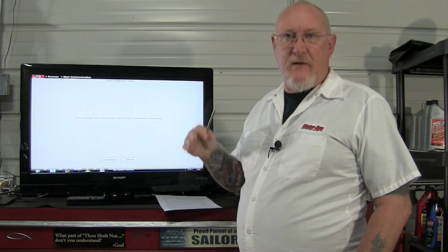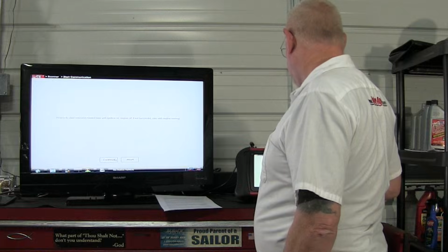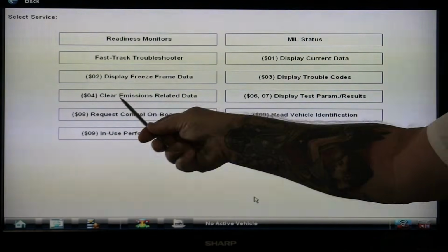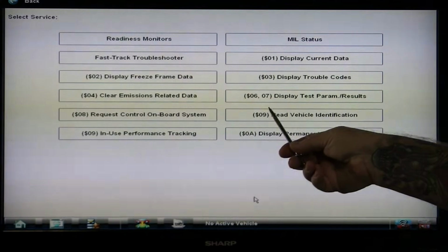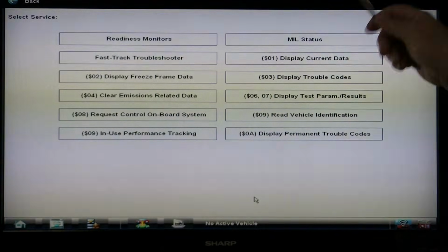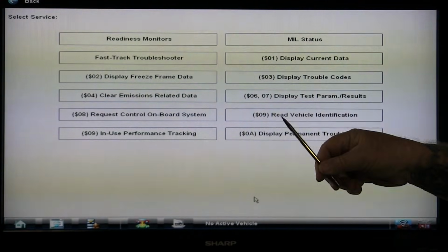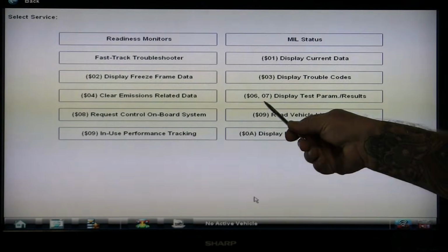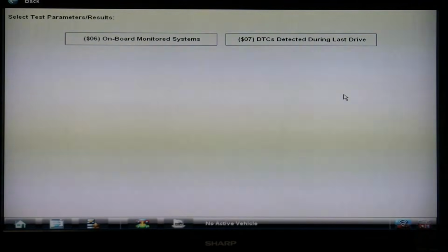Take a screenshot of it, take a picture of it with your phone, whatever you've got to do so that you don't lose that valuable information. Now lastly, you're going to see here there is no mode 5 listed on this screen. Now why is that? Pete, didn't you just say that all the Global OBD II stuff is the same? Well, it is, but remember what I also said, that on CAN equipped vehicles, like our guinea pig here, it's incorporated in mode 6. So we'll just take a quick look there.